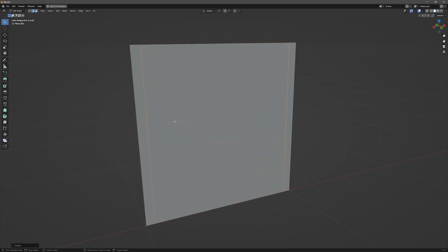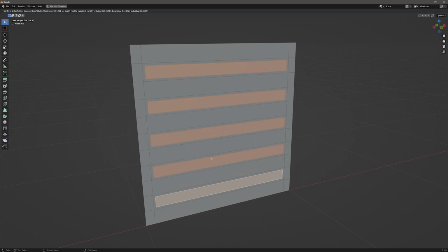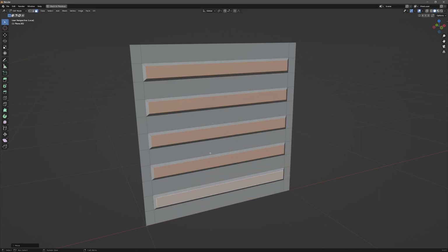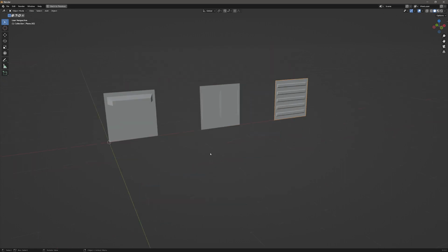And then I'm going to create 10 slices using my mouse wheel to roll up, and I'm going to leave them there by hitting escape. I'm going to select these 5 faces. I'm going to use inset one more time, and then I'm going to just grab and pull them out on Y just to give them some relief. These are going to be the areas that go at the top of my building.